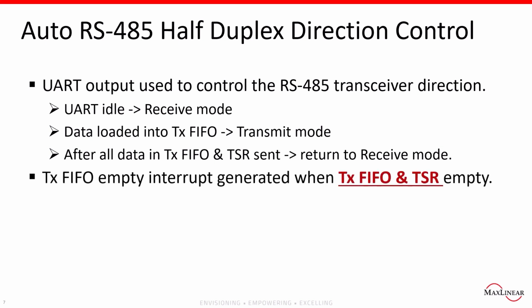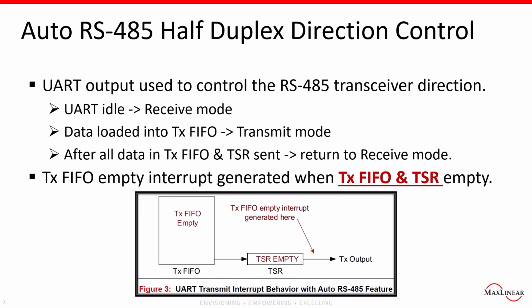The other change when the feature is enabled is the TX FIFO empty interrupt will be generated when both TX FIFO and TSR are empty. This will avoid the extra effort of monitoring the TSR status.